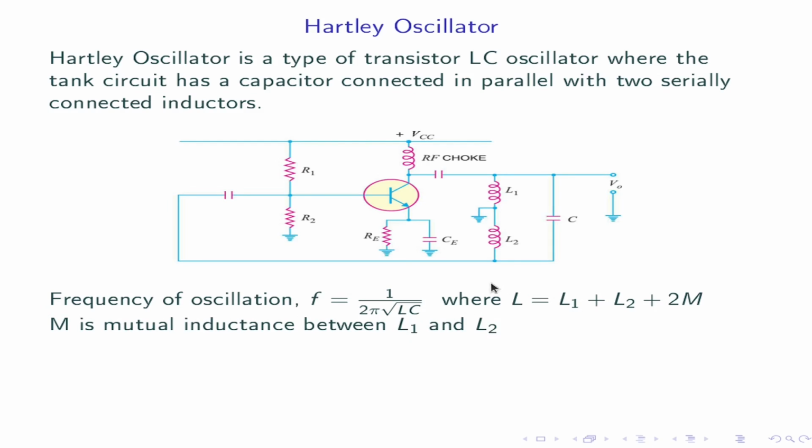Here the output voltage is across L1 and the feedback is across L2. This connection gives a phase shift of 180 degrees. The voltage fed back to the transistor provides positive feedback. Thus, a phase shift of 180 degrees by L1 and L2 and a further phase shift of 180 degrees provided by the transistor mean that feedback is properly phased to produce continuous undamped oscillations.